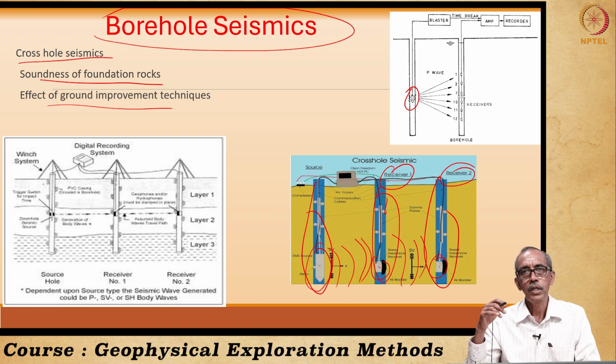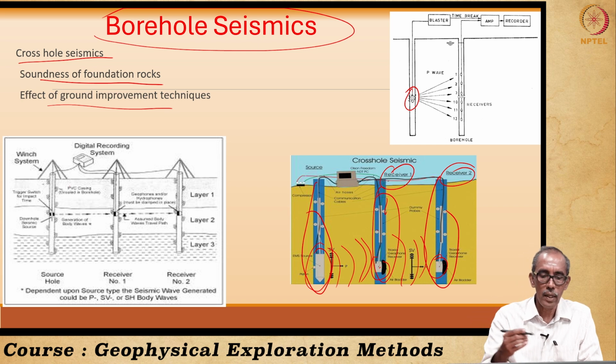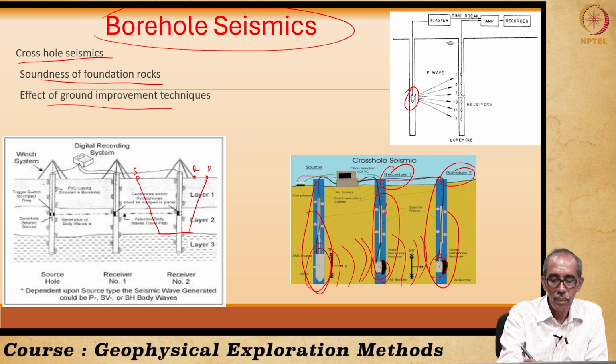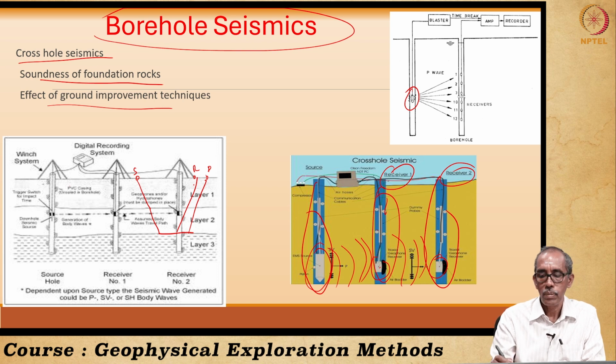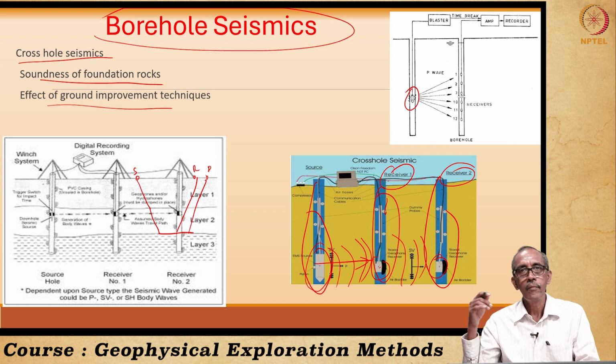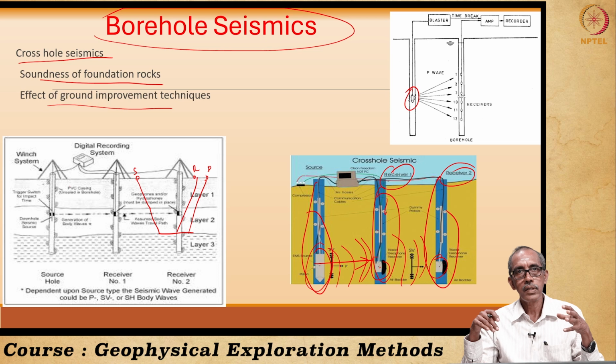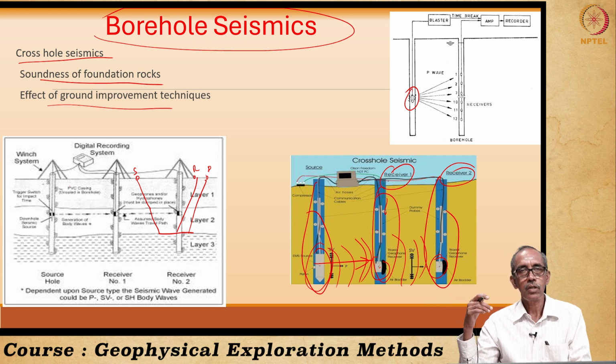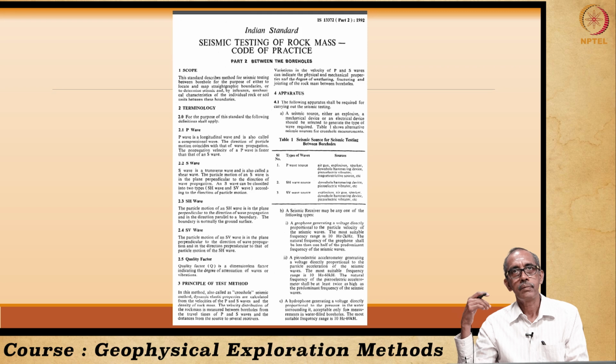This method is much more direct, whereas in the seismic refraction method, this is the source, and the geophones, the receivers, are kept at different locations; the shock waves go in and get refracted back, isn't it? Whereas in this method, we have gone down below the surface of the earth and we are energizing the ground. The effect of this energy is measured in some nearby boreholes. That is why it is called borehole seismics.